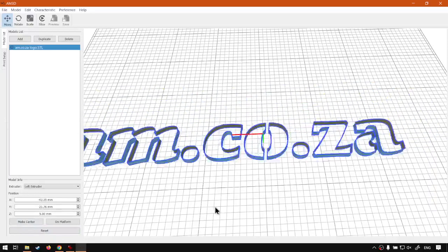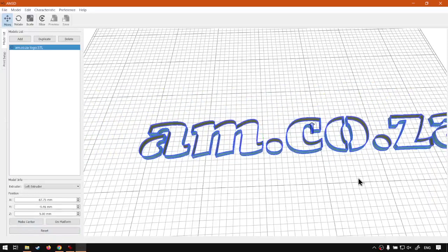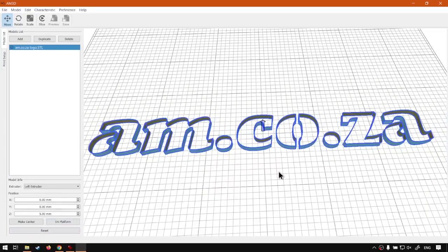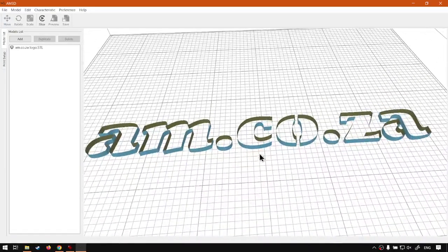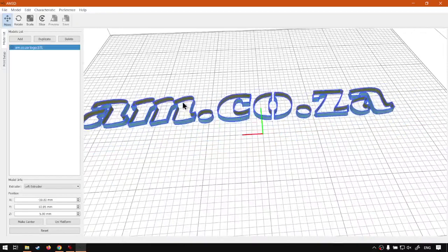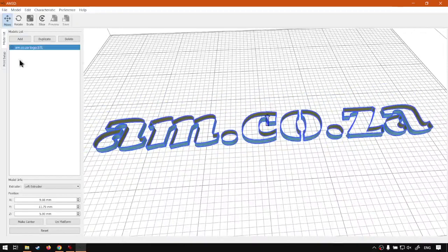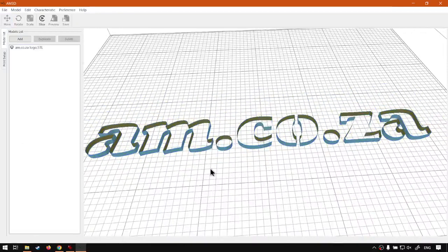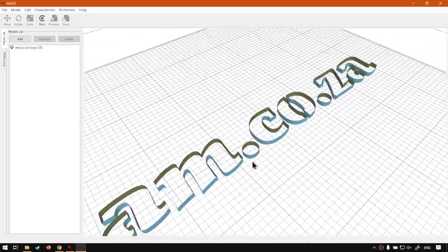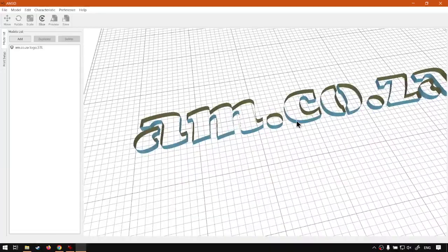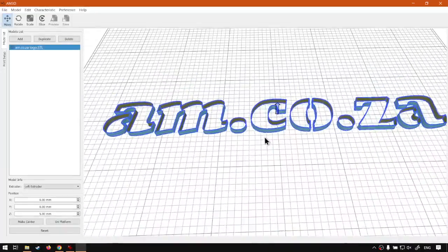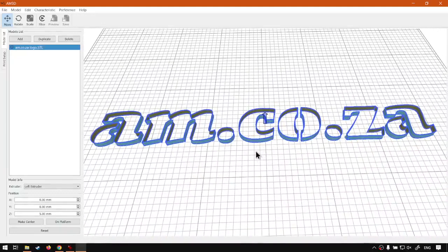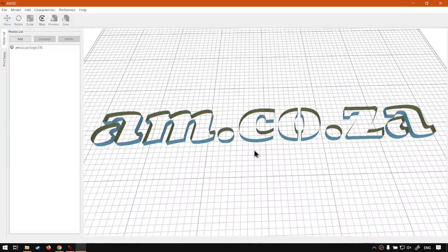If you want to rotate it, it might be frustrating, and then as you will notice, there's no undo, you'll have to reset it. So first deselect, then if you left click, you can rotate. If you have it selected and you left click, it will move your object. So just something to keep in mind. So for that reason, I like to rotate with my right mouse button, because it's slightly safer. If I have something selected and I right mouse button, nothing happens. But yeah, so that is the two methodologies of going about it.